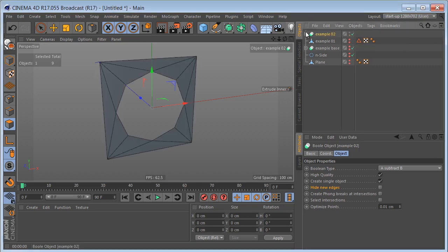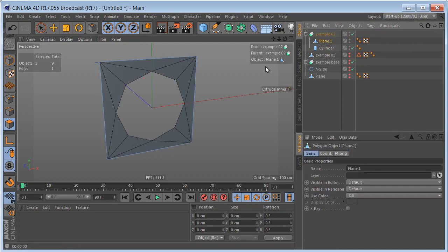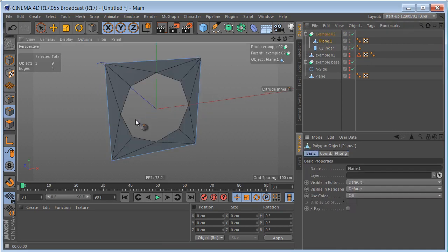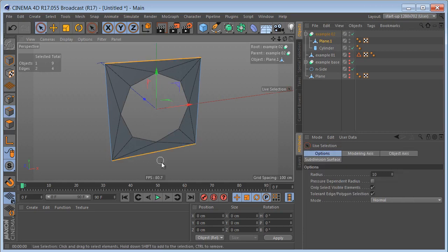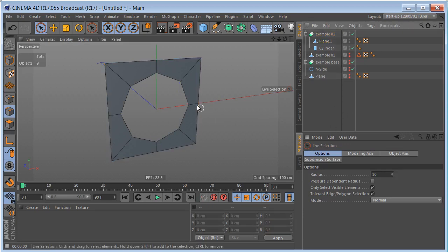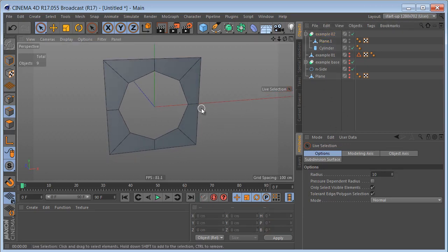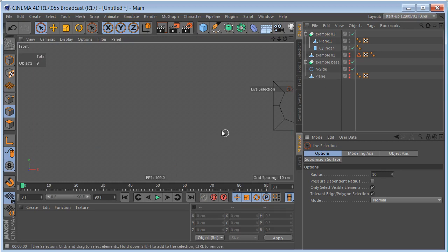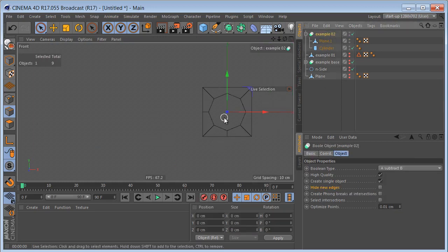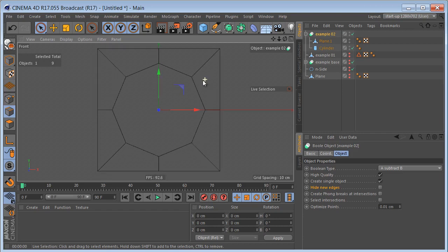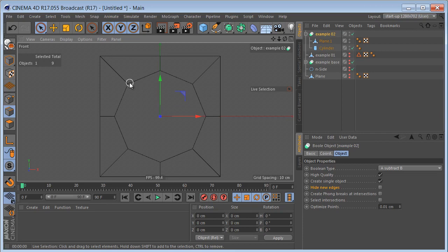And we're going to start the same way we did before. So we're going to add the vertical and horizontal edges. I'm just going to grab these edges here and connect them, and I'll connect these edges here. So we're getting the same geometry as before, but this time I want to do things a little differently. I don't want to create these edges that go to the corners here. I want straight geometry. So I'm going to create edges from this point of the cylinder straight up to this edge here.